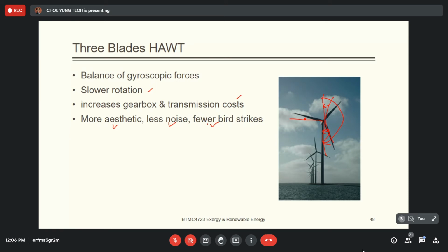According to the study, three blades, four blades and five blades theoretically generate the same amount of power. It's not that when you add a fourth blade you will get more. Yes, supposedly you will get more lift force because you have four blades absorbing the lift force from the wind. But at the same time, because you have more blades, some of the time your blade will reach the turbulent flow location earlier, so the efficiency will drop. And again, you need to add extra material.